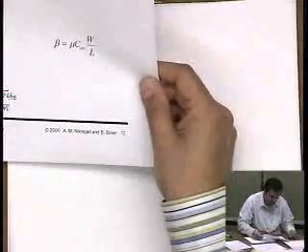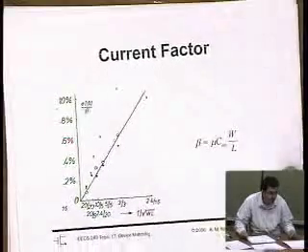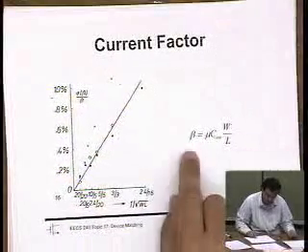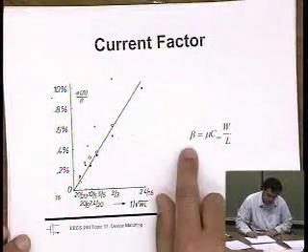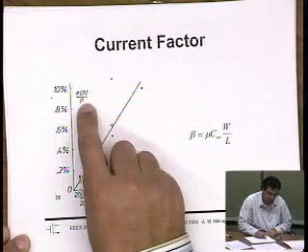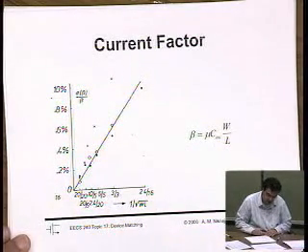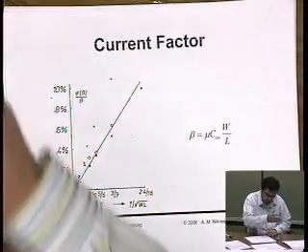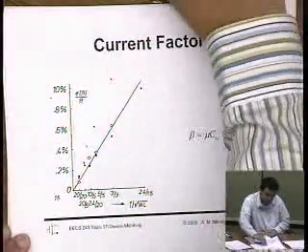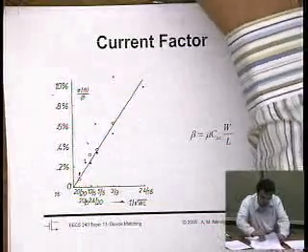Okay. This is some data again from Pelgrom's paper, and it's showing you beta mismatch. So this is a standard deviation of beta normalized to beta as a function of device size. And so you can see here, in answer to your question, we can compare that to the threshold mismatch.